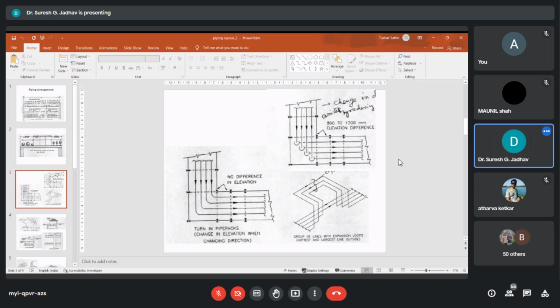So here there is a combination of 90-degree and 45-degree elbows that may be used, considering the final layout in piping engineering installation. The final stress analysis will be done after the routing is finalized. A primary check for the isometric is required to establish the requirement and size of expansion loops, as some pipes are going down and some pipes are going up.